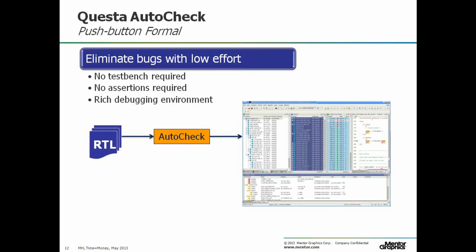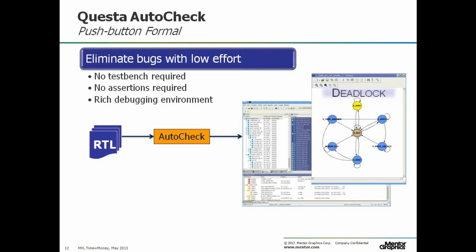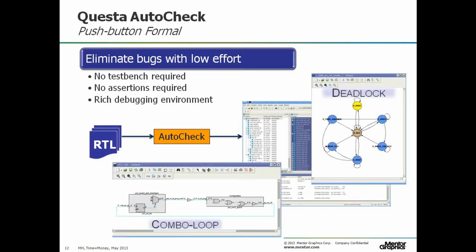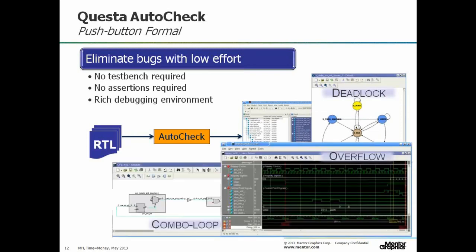You can constrain that RTL if you require it to, using SVA or PSL or whatever it might be. So again, as I said, you don't need properties here. You're defining checking against a predefined rule set. But the beauty here is it catches a lot of bugs very easily, very quickly, and some of these things you'll never catch in simulation. So true arithmetic exceptions, deadlock, livelock, other state machine issues, complex loops through latches, through hierarchy that you may not be able to chase down using traditional techniques.